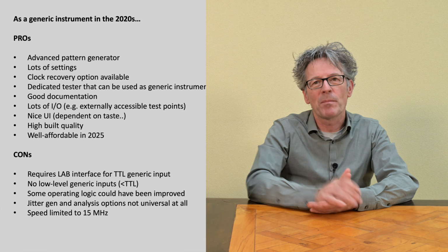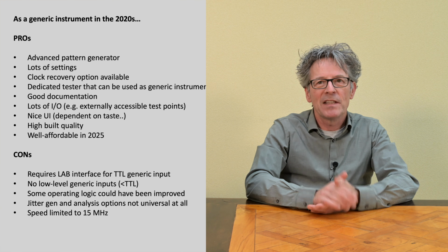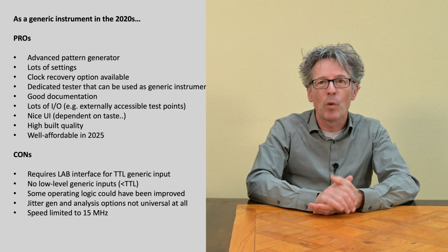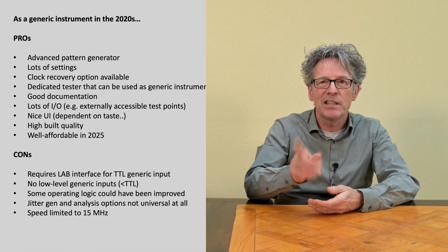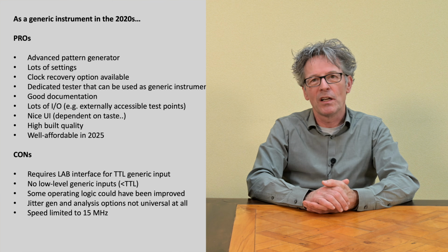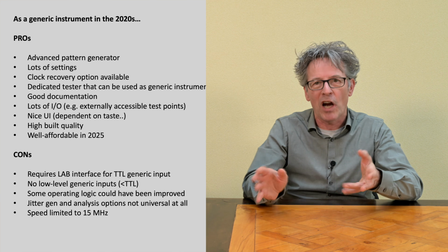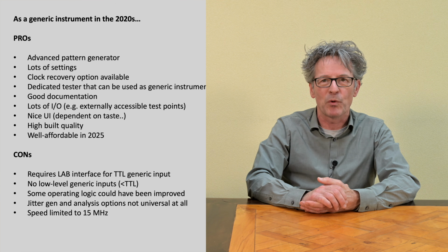Yeah, maybe I should give some examples here. One of them would be, for example, when you're running in synchronous mode, it still offers you all the options for the settings that actually should only be valid in non-synchronous mode, like for example the length of the data words and the start bits and the stop bits and all that type of stuff.